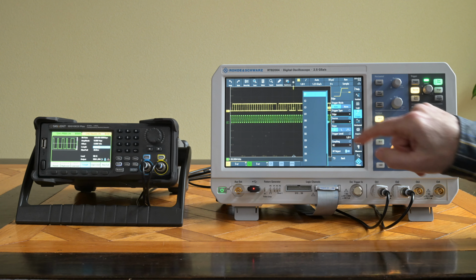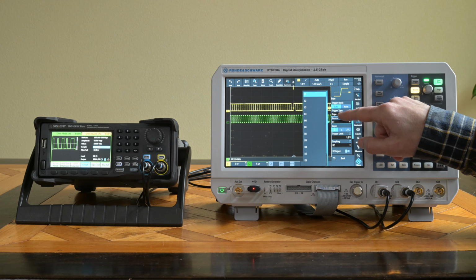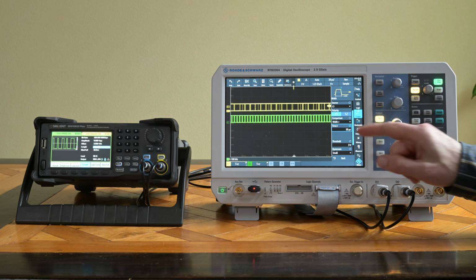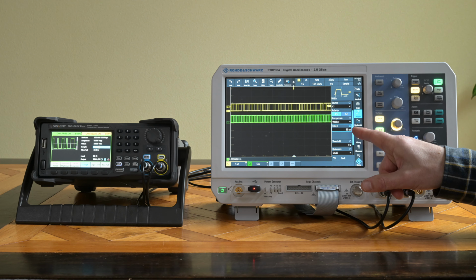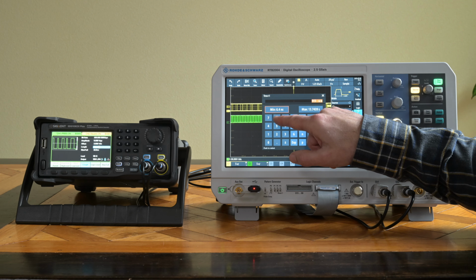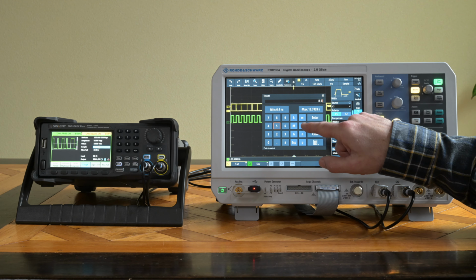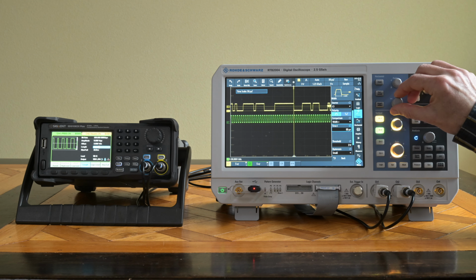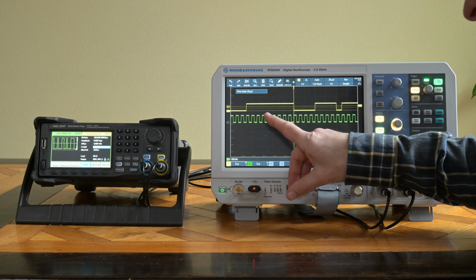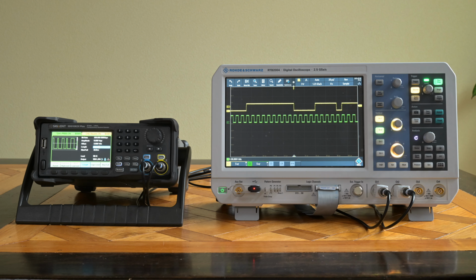We can trigger on the signal itself, and we can decide to trigger on a certain width of the signal. Currently my scope is triggering on a pulse wider than 95 microseconds, so it would only trigger on 10 bits or more, but I have exactly 9 bits, so I could do 85 microseconds. So it should not trigger on 8, but it should trigger on 9. And yeah, we got it triggered. We can also inspect that manually. There should be 1, 2, 3, 4, 5, 6, 7, 8, 9 ones in a row. Yeah, so this looks exactly like the signal should be looking like.